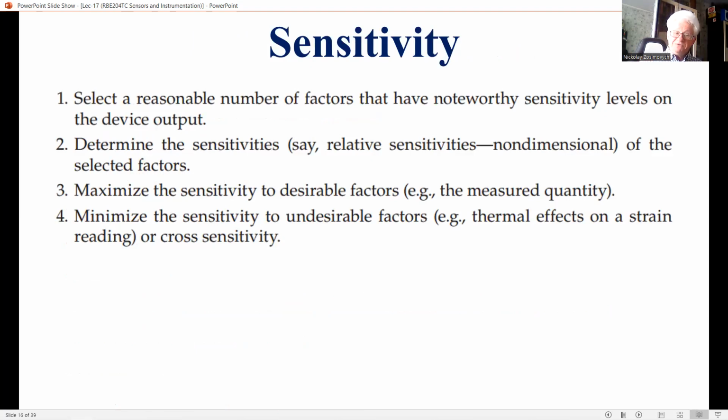The sensitivity of a device or transducer is measured by the magnitude (peak, root mean square value, or tensor) of the output signal corresponding to the unit input or measurand. This may be expressed as the ratio of incremental output to incremental input, like the slope of the input-output curve of the device, or analytically as the corresponding partial derivative in the input-output relationship.